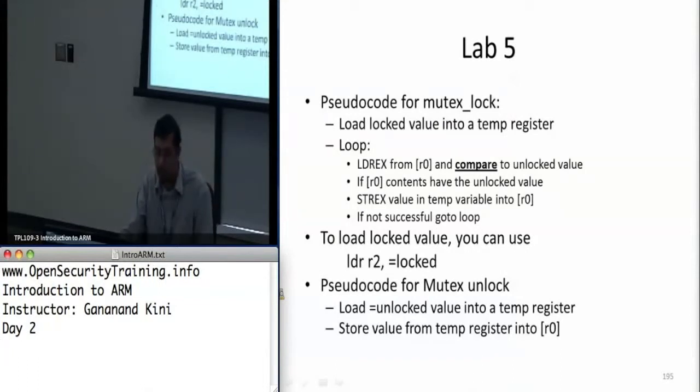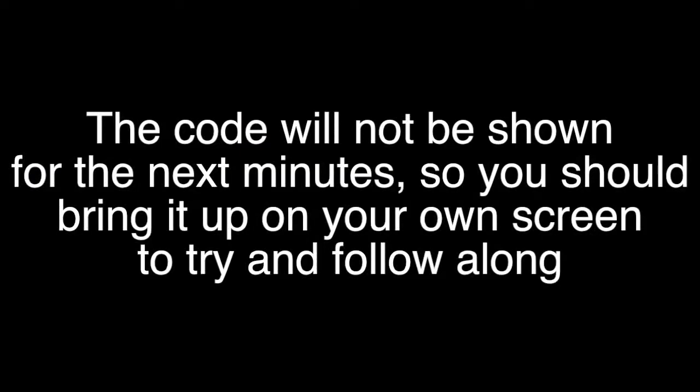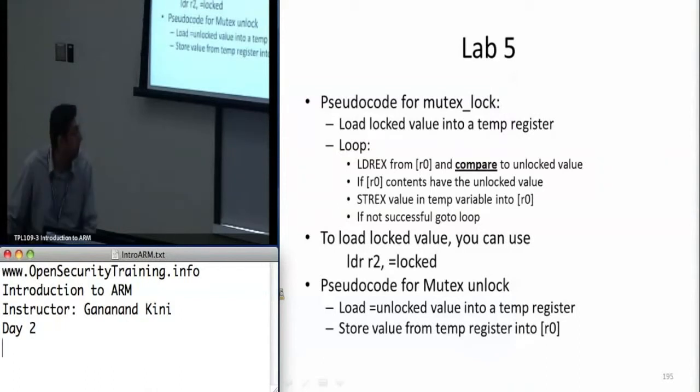And if you look at the code under atomic.c, you'll notice that there's an argument being passed to lock mutex, and it's called mutex locks, and it's defined as an unsigned integer up here, and it's initially set to the value unlocked, which is defined to be 0, and locked, which is defined to be 1. So this is just for convention, but those values could be anything.